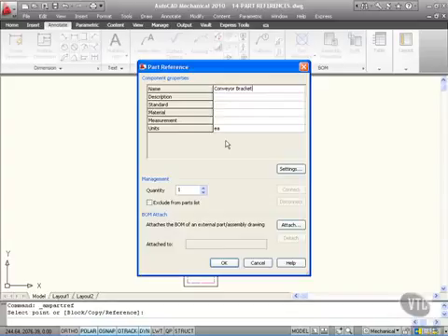So conveyor bracket, description, well that's easy enough, isn't it? It's going to be a bracket. Now a lot of this is very self-explanatory. The standard that you're working to is going to be ISO, and the material, let's say it's steel, and the measurement there I'm not going to worry about too much, but in this particular case we're working in millimeters, so I would actually type in there mm for millimeters. Now you'll notice I can't type anything in there right now because I'm working to the ISO standard. Notice though, units each. That's why I can't put a measurement in there.